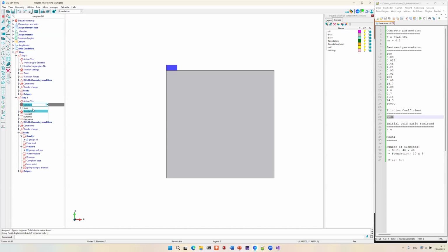So now we want to perform a static simulation. So we change that. And what we also want to do, we don't have to actually, but just to give you a bit more insight, is change the time integration. You can specify an initial time step, so the time increment with which this step starts. And then from there on, we use an adaptive time incrementation. So if the convergence rate is very good, we allow the solver to increase the time step, so to accelerate the simulation, but we can also cap that one, right?